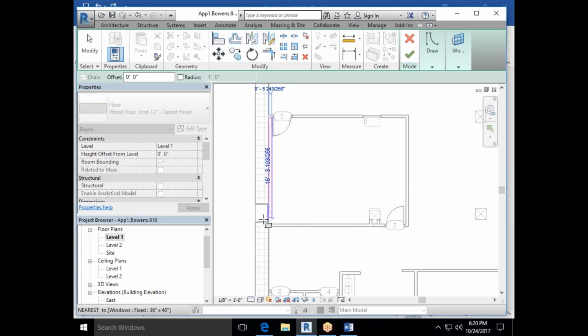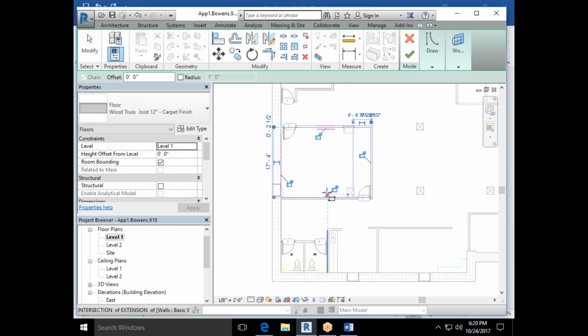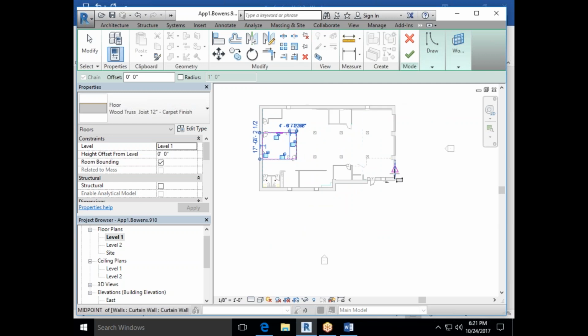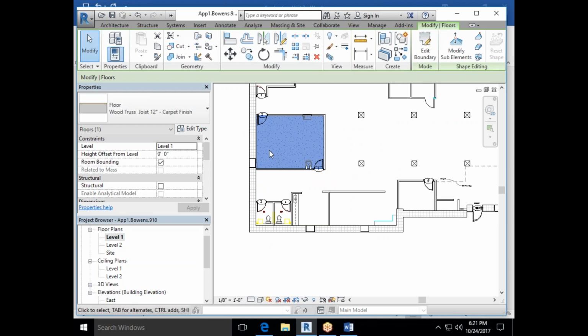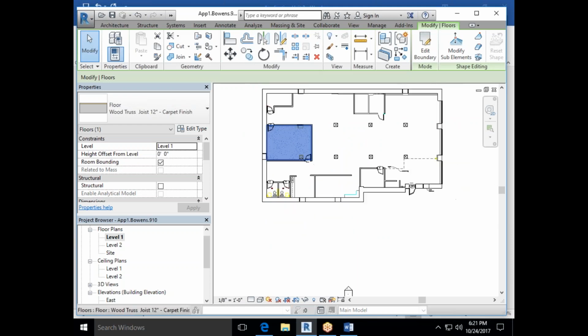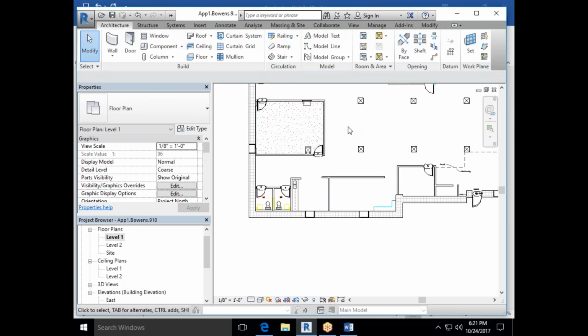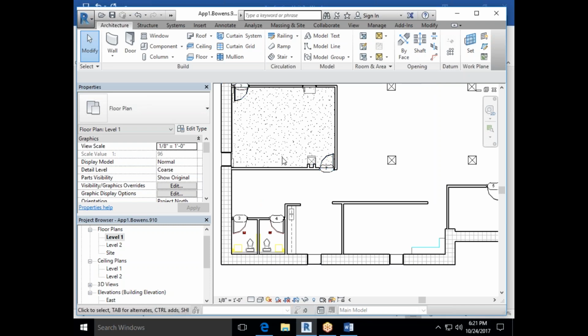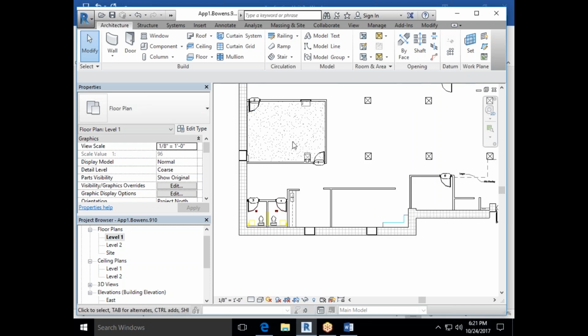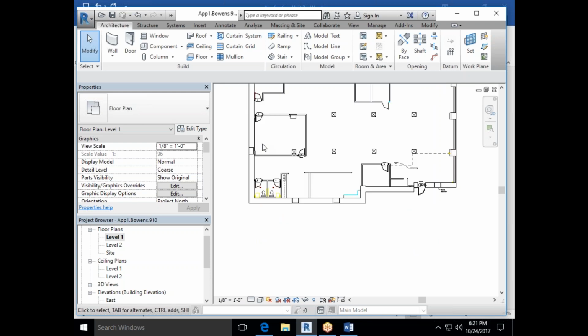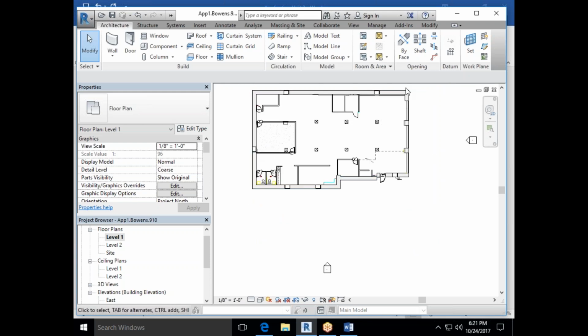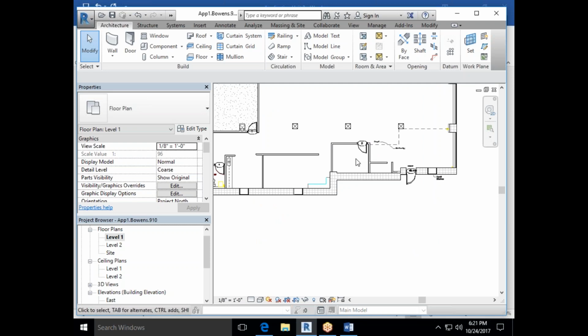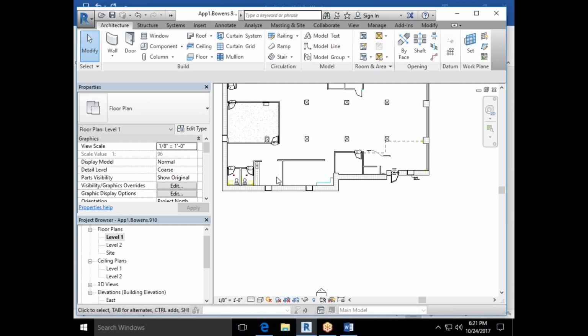We can put our floor and we can draw a really nice clean line, which is what the hope would be, following all the walls. But once we get our floor in here, we could have covered this whole area and gone through the walls, and it would still be fine. The walls are not going to affect how we have our carpet placed in the floor plan. So there is my carpet. And then I'm going to show you how to adjust the materials of your carpet later on. But you could do all over by drawing all your boundaries. You could do individual rooms, drawing boundaries, or rectangles, but your walls do not affect it. Does that make sense to everybody?